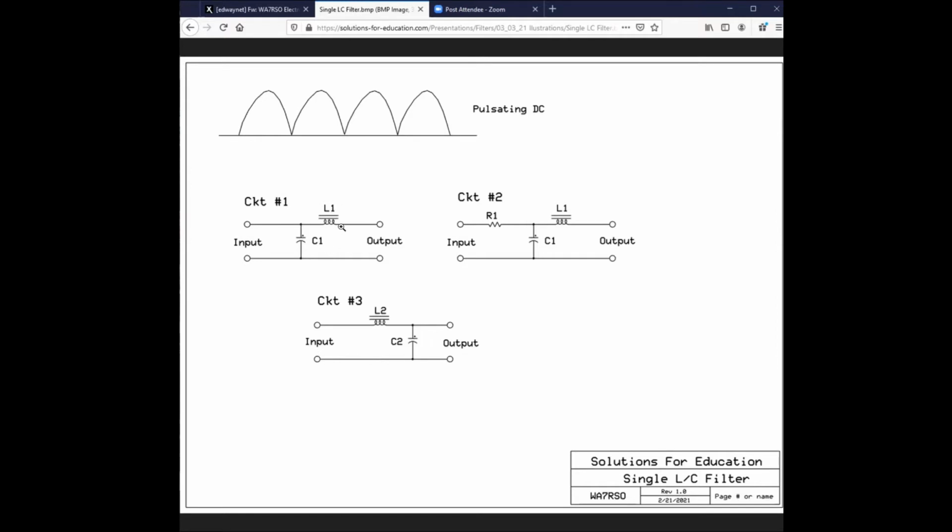The engineering staff, if you want to look at it this way, has a formula for this. They say the voltage developed as the magnetic field collapses depends on the rate of collapse, and they have a formula that says E is equal to the change of flux versus the change in time. E = dφ/dt is the correct formula for it.